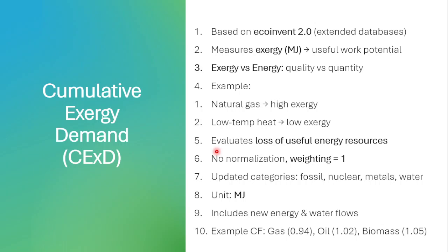By this methodology, you can easily distinguish which of the components has the highest exergy destruction rate, EDR. So we can solely focus on it for optimization or better performance, in order to improve the efficiency of the total system.